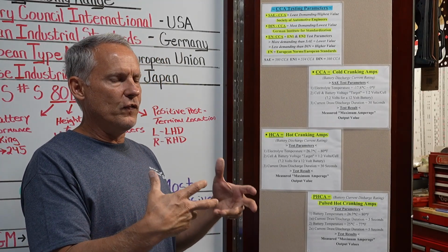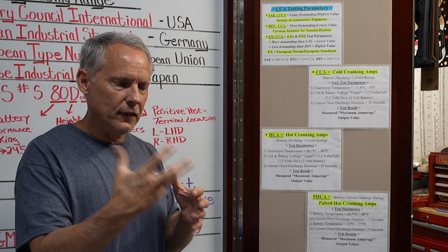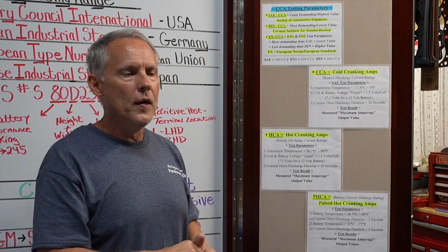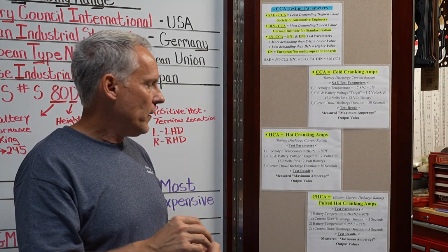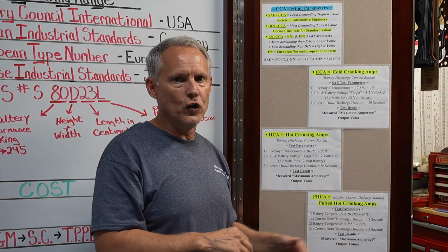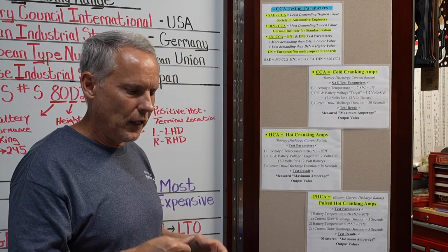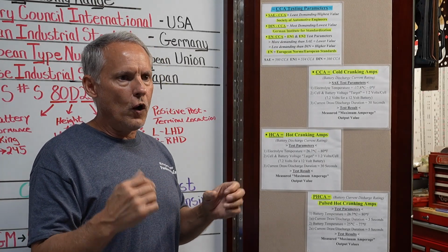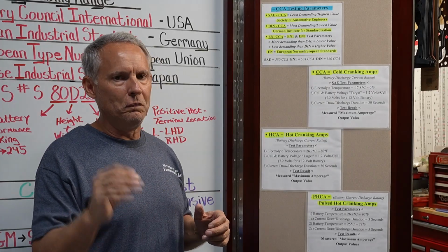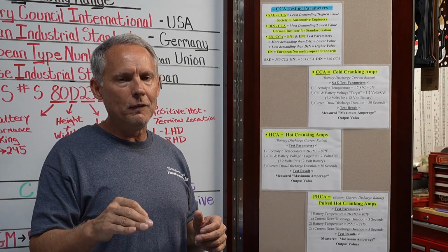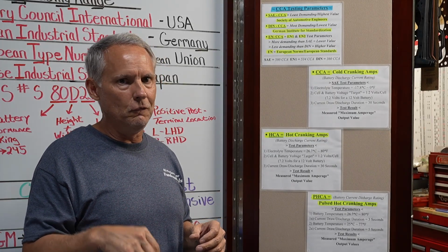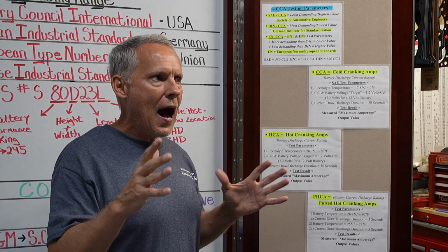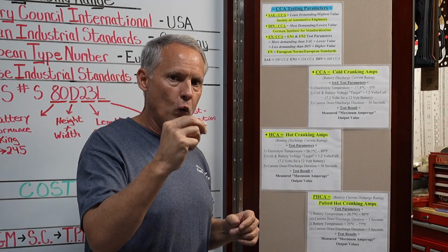The battery itself is rated, or designed, in such a way that it can deliver a lot of current flow in a very short time, but only for a very short time. That's why it's rated for such a short duration, only 3 seconds. Like I said, you take those little jump packs, and some of them are decent size nowadays, but you'll notice that they'll spin the engine over really fast, but not for very long. It better start, because if you do that a few times, it's not going to want to crank over at all anymore. So it's a very high discharge current for a very short duration.